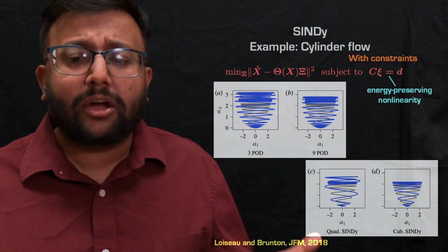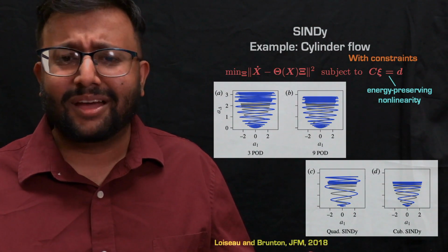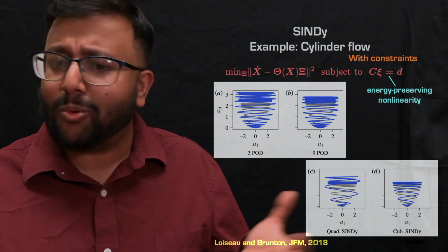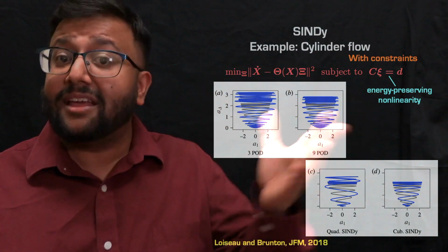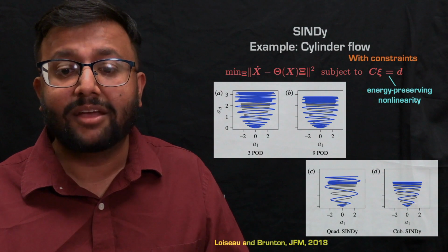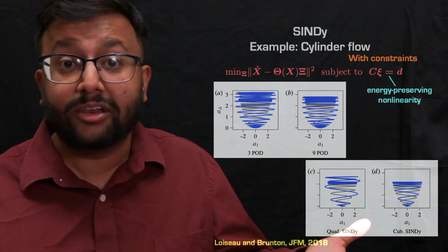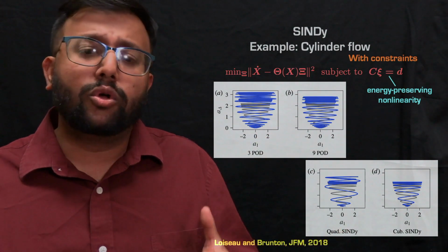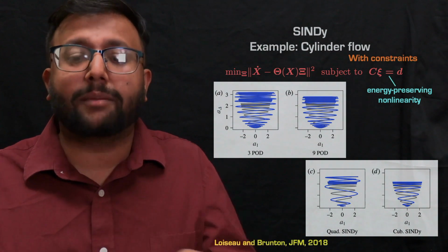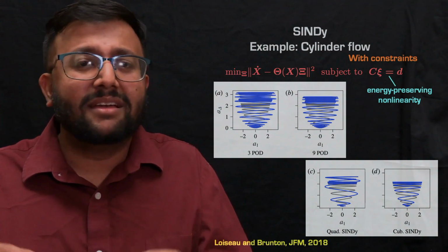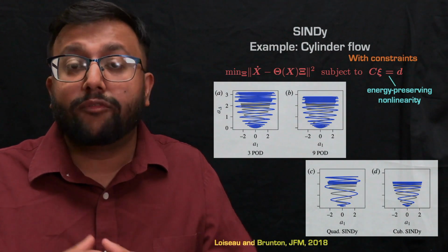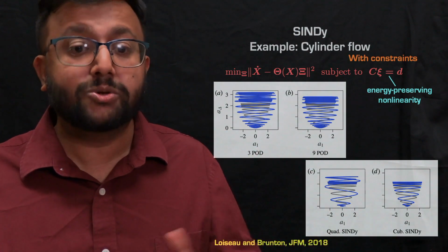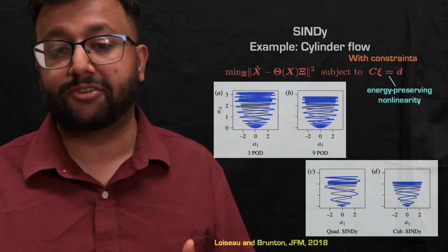Now this cubic order of the polynomial is quite curious, right? Because the Galerkin projection model that we obtained had a quadratic nonlinear term. So somehow these cubic polynomials are providing some kind of closure model for off limit cycle evolution of the flow trajectories.